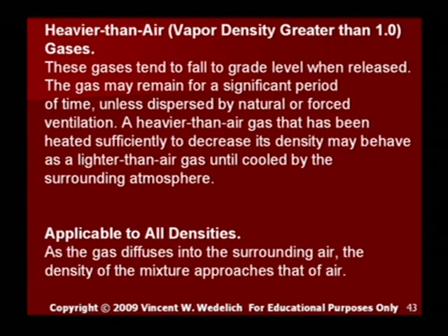Heavier than air, vapor density greater than 1.0 gases. These gases tend to fall to grade level when released. The gas may remain for a significant period of time unless dispersed by natural or forced ventilation. A heavier than air gas that has been heated sufficiently to decrease its density may behave as a lighter than air gas until cooled by the surrounding atmosphere. Applicable to all densities, as the gas diffuses into the surrounding air, the density of the mixture approaches that of air.